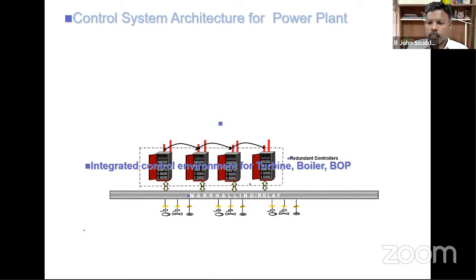to the pressure transmitter. Once the pressure transmitter is powered up and there is a process pressure, imagine it is of the range 0 to 10 kg, and the actual process pressure is 5 kg. The output is given in terms of 4 to 20 milliampere. For 0 kg pressure, it would show 4 milliampere. For 10 kg pressure, it would show 20 milliampere. For 5 kg pressure, it will show 12 milliamperes.